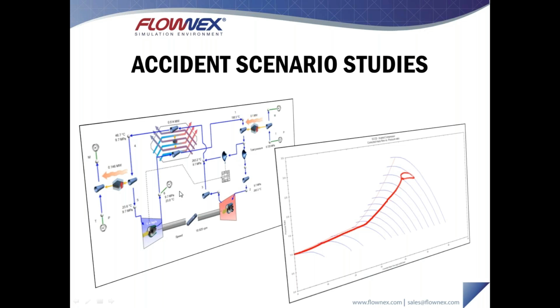Another action was also implemented inside of the actual actions manager that I showed earlier, where we did the step test. This was then used to control the position of this turbine control valve, and adjusting this position over time gave us a way to remove the power inside of the system. So it allows the system to slowly lower the mass flow rates and then shut the compressor and turbine down gradually. So yeah, in this scenario, we were able to look at how the system would behave in an accident scenario.